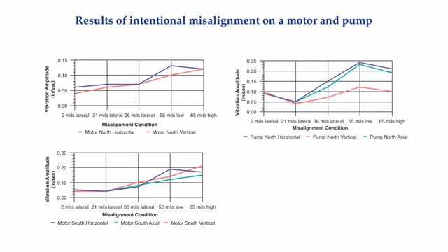At the inboard or coupling end of the pump, when the unit was misaligned 21 mils laterally, the vibration decreased in the horizontal, vertical, and axial directions. At 36 mils of misalignment, the vibration increased in the horizontal and axial directions, but still didn't get back to the well-aligned vibration amplitude in the vertical direction.